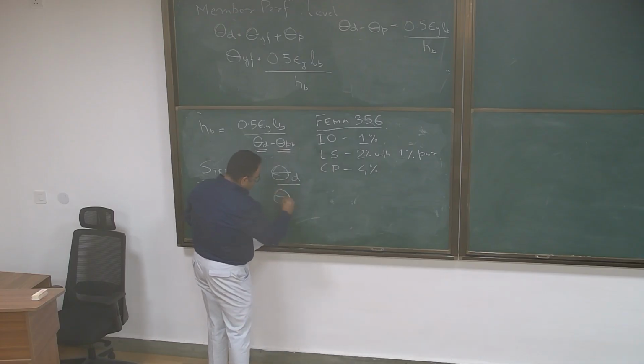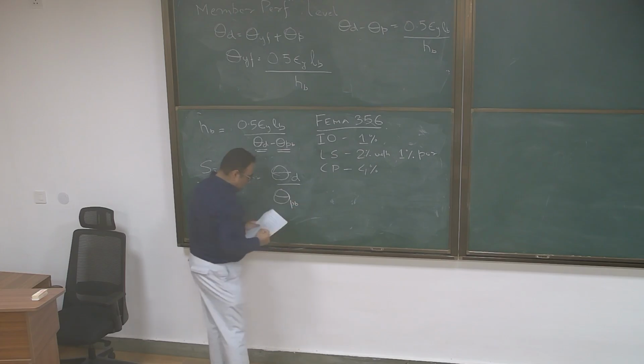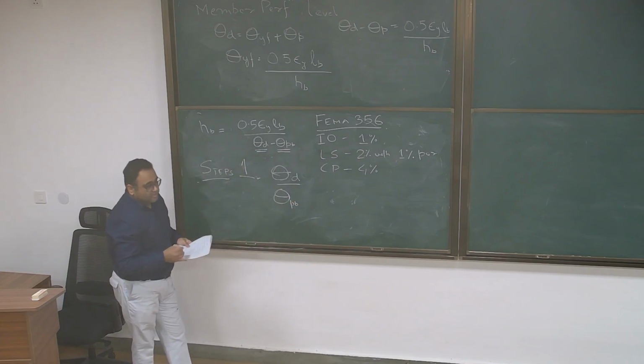Okay, so what are the steps that we take to design with UPBD, or Uniform Performance-Based Design? As well as a hazard level, right? Or a number corresponding to that hazard level. So this is your interstory drift that you need to decide upon. And then you also have to decide what hazard level your theta PB corresponds to.